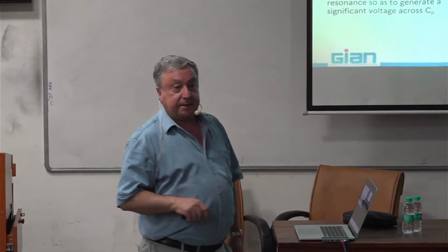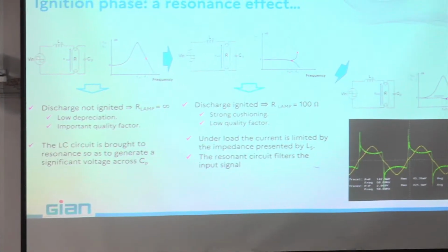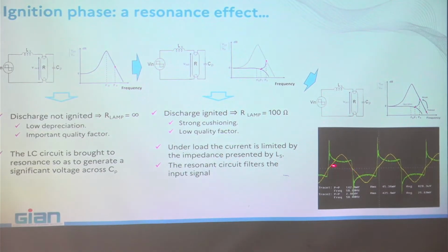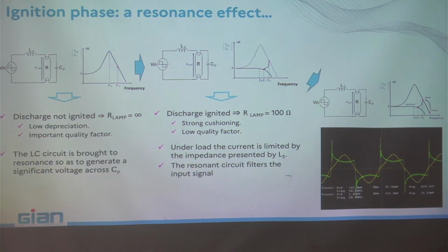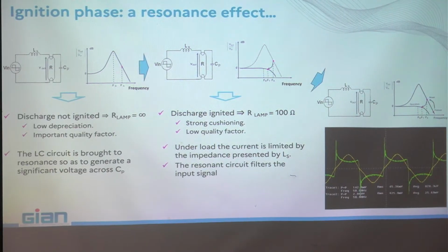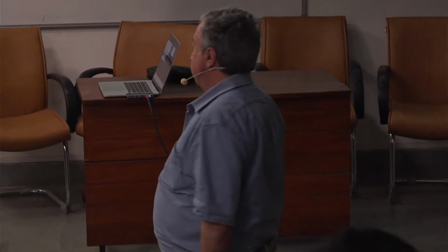And you observe what I said: this is the voltage and current measured on the lamp. Here you see that they are in phase. That means even if the lamp is a nonlinear resistor, a curious nonlinear resistor, it is still an ohmic resistor and doesn't cause any phase shift between voltage and current.